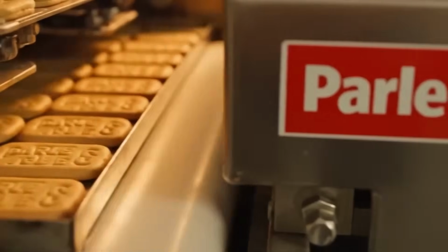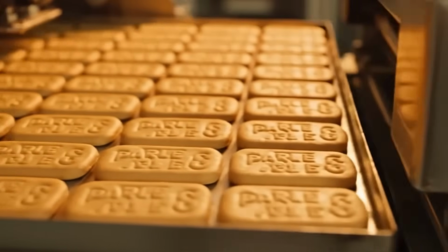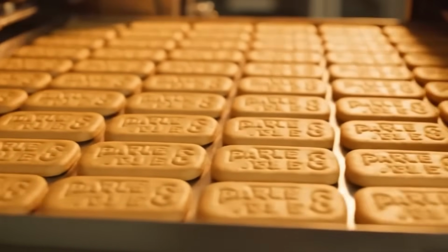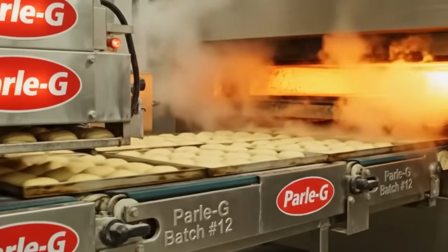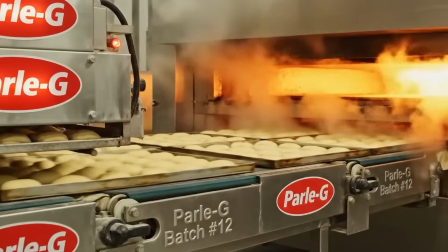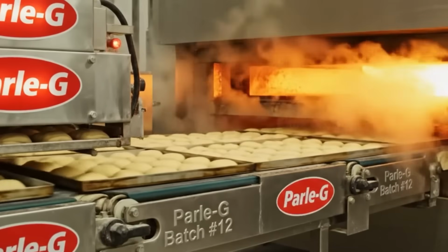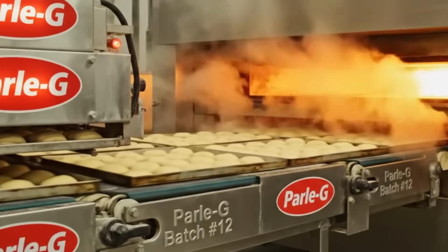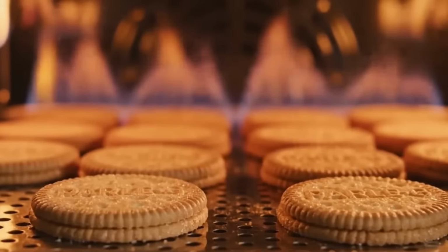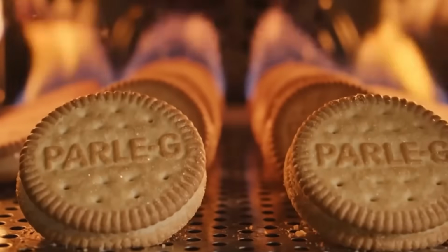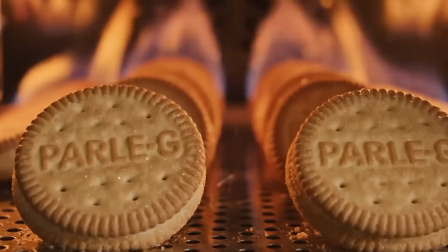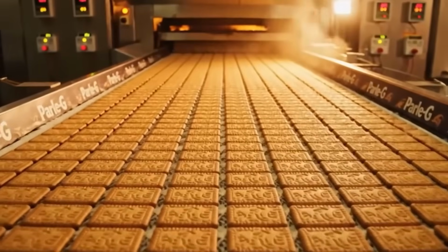After baking, the biscuits exit hot and fragile. They move to cooling conveyors where they firm as fats resolidify. Cooling also allows moisture to redistribute slightly. For crisp biscuits, cooling air is often dehumidified because biscuits can absorb moisture from humid air and lose snap. Cooling is staged, so thermal stress does not crack the biscuits.